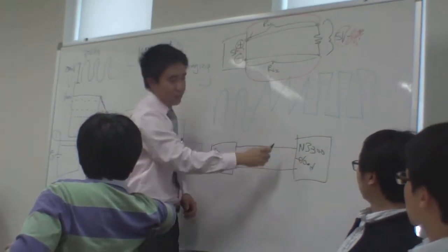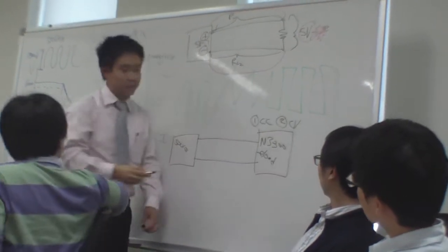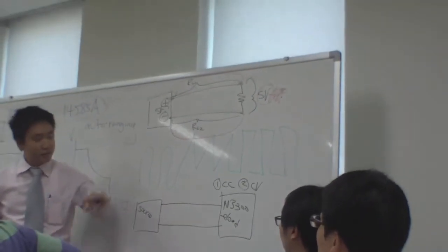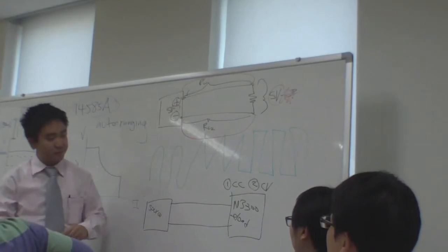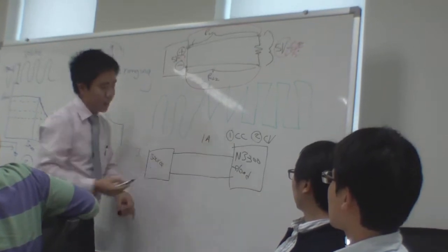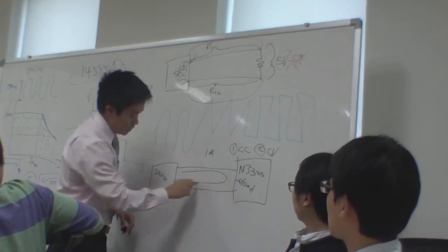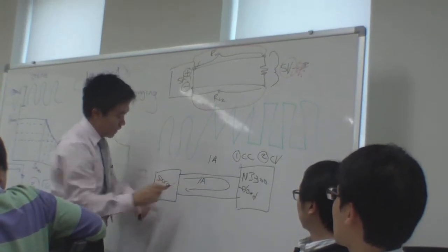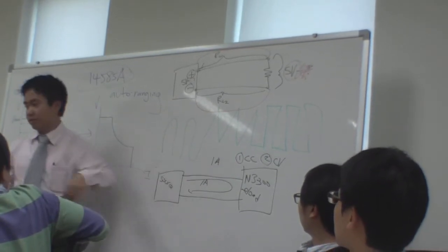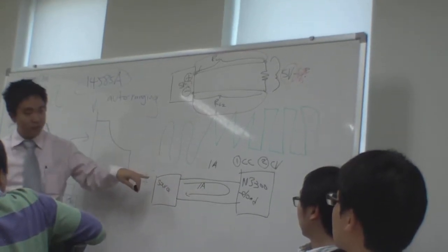On this guy, on the ELO, you have 2 choices: constant current or constant voltage. If you choose constant current, let's say you select it to be 1 amp, this will pull 1 amp from your source, and its entire job is to regulate this 1 amp. So 1 amp only, not 2 amps, not 3 amps, just 1 amp going through the circuit.